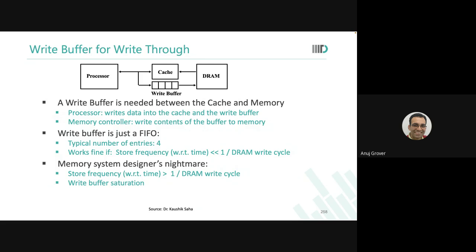So these are topics linked to computer architecture. There are again many algorithms to help you arrive at those. What I'm pointing out over here is that between L1 cache and L2 cache also, just for the write operation, you may need to put a small buffer. This buffer could be like a FIFO. Is that okay?